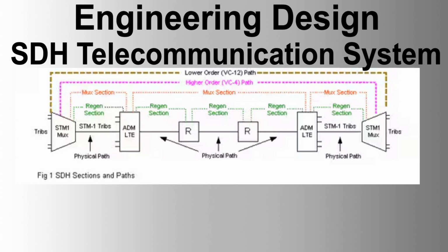Security. The system shall be protected with a security system using usernames and passwords, offering varying levels of access for operators, system managers, technicians, and view-only users. Automatic device detection. The NMS shall automatically detect and display new devices on the telecommunication system and indicate disconnected devices as an alarm.